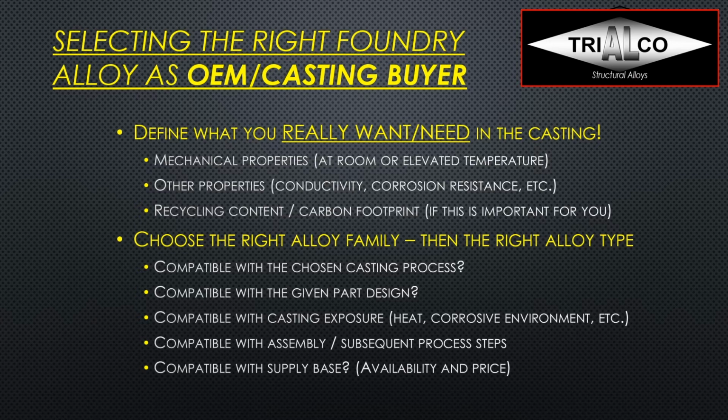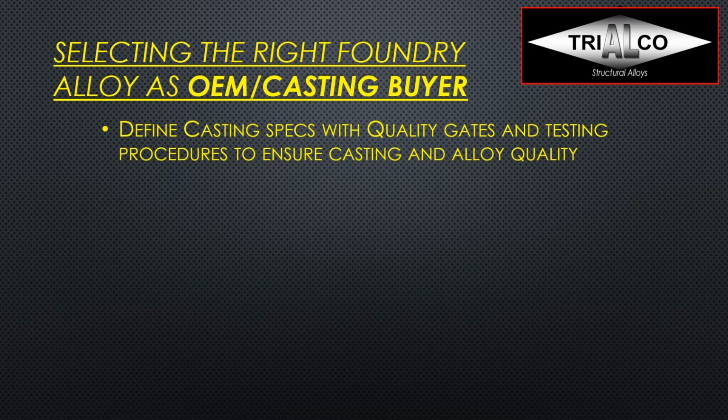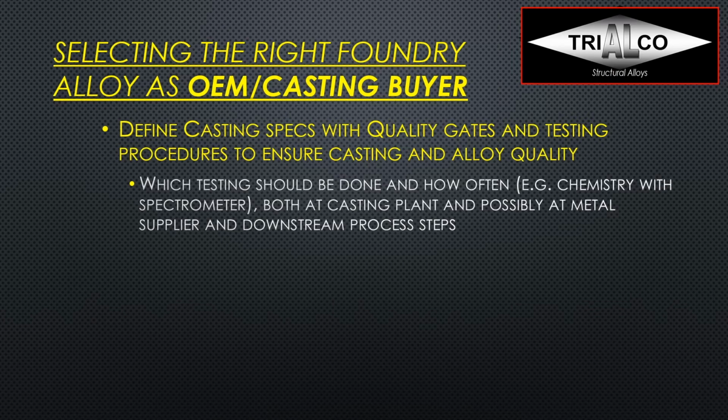So availability and price. Now I would recommend you define casting specifications with quality gates and especially testing procedures in place to ensure the casting and alloy quality. So rather than specifying a certain brand name that you've heard has high quality, really define how you want the quality to be measured and to be tested. Which testing should be done how often?